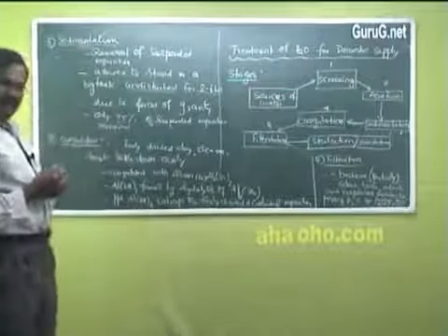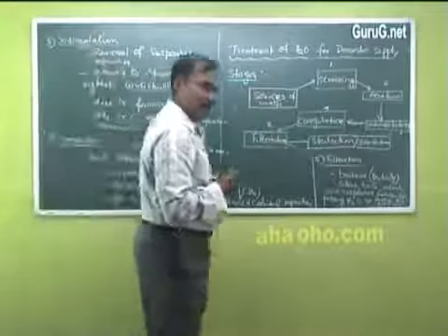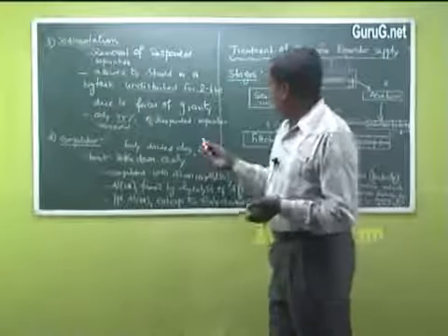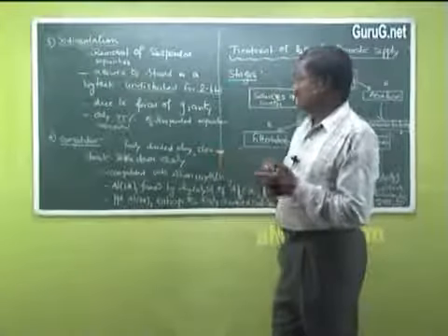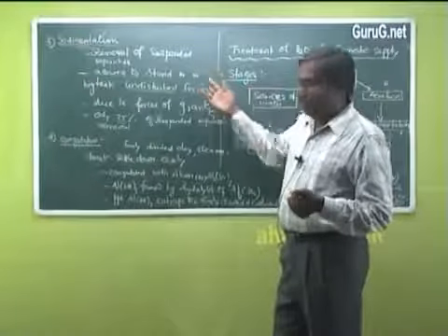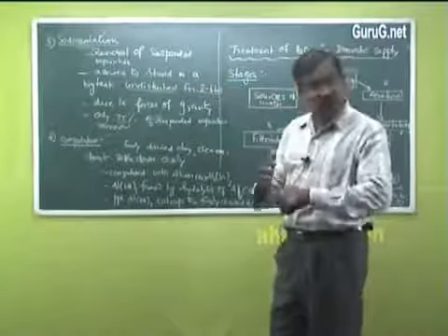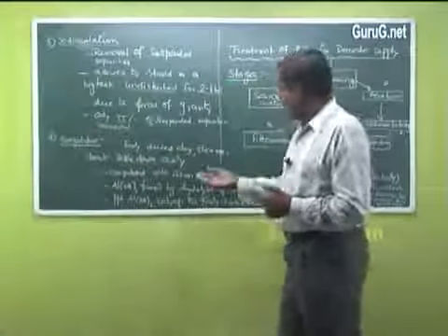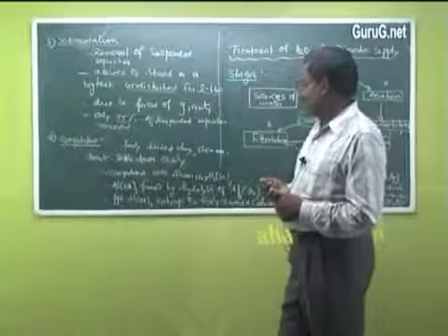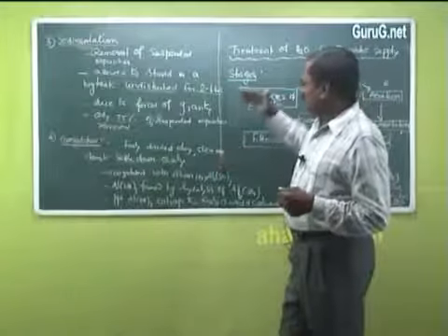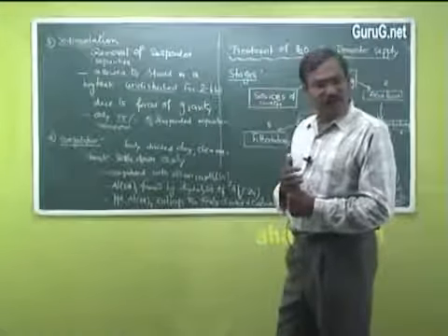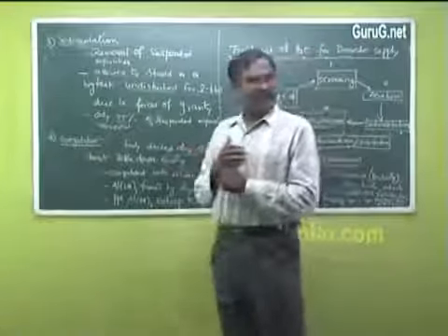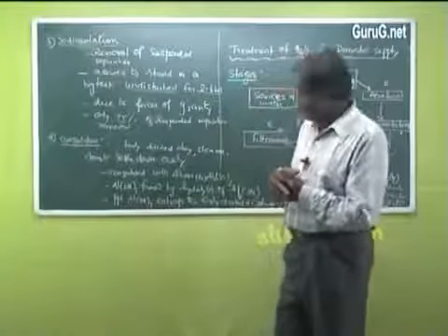Sedimentation is carried out without adding any chemicals, whereas coagulation is to remove finely divided clay and silica, which do not settle down during sedimentation. They are made to settle down by adding some coagulating agents like alum or aluminum sulfate. These chemicals make the clay and silica settle down as a precipitate. So how does this settlement take place? How are the particles made to settle down?